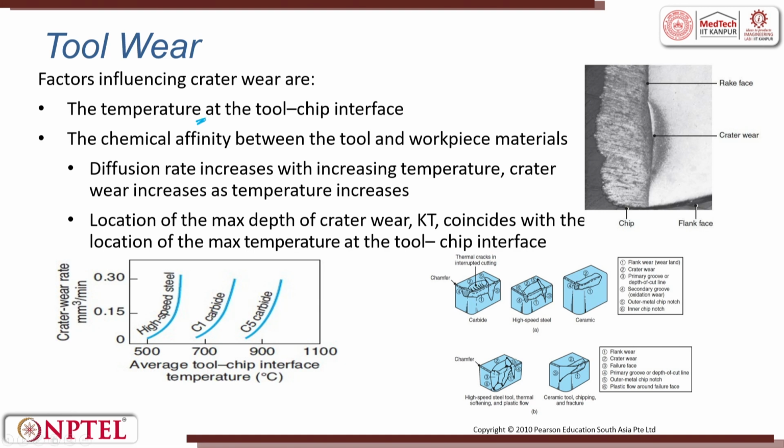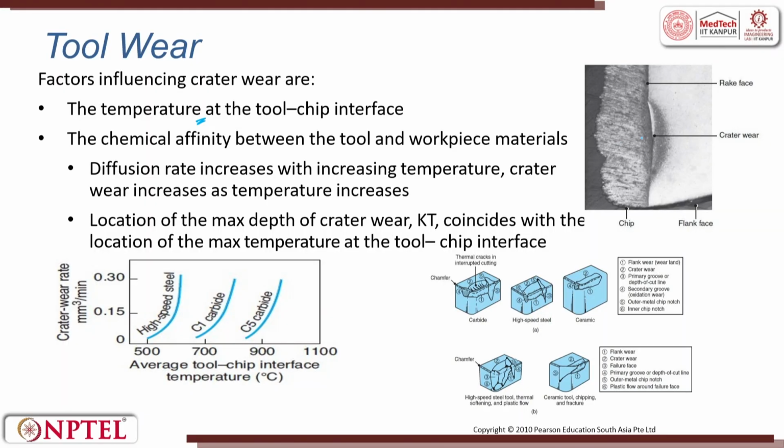This temperature leads to diffusion. We saw in heat treatment that there is a diffusion happening, right. Because of this diffusion there is a chemical difference, and that leads to wear. The chemical affinity between the tool and the workpiece material comes into play. The diffusion rate increases with increase in temperature, which relates to the crater wear. The location of the maximum depth of crater wear, KT, coincides with the location of the maximum temperature of the tool-chip interface.